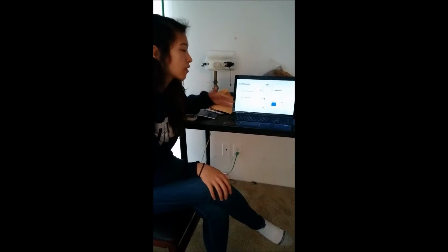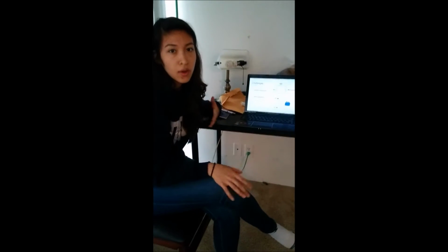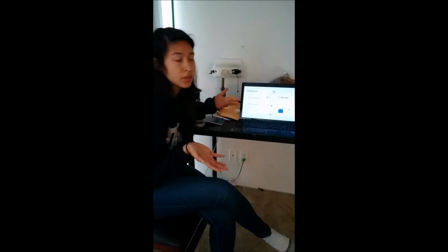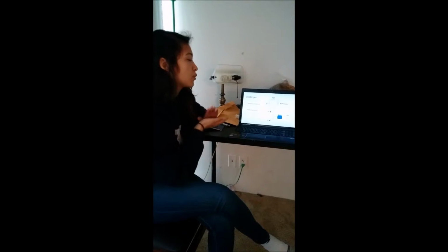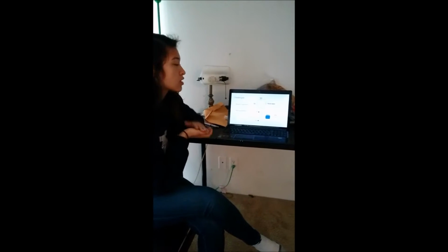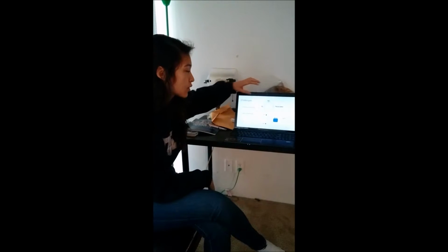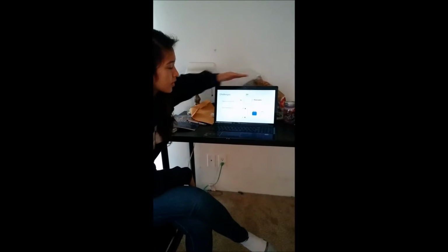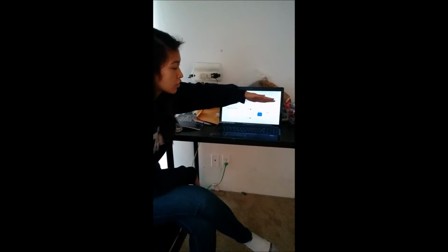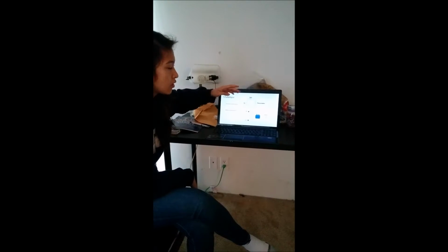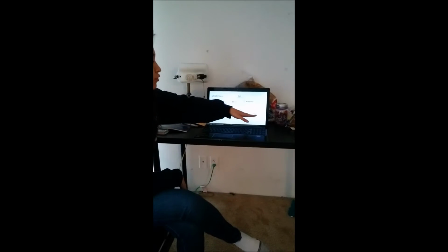Meanwhile, we also had to deal with where to place the motor. How would we create a circuit that would allow current flow in either direction? And we discovered that to do this, we would need to actually connect the motor to two different sources of voltage. And we could then connect the motor to ground such that we could create a variance this way, such that current would flow from high potential to low potential. Alternately, we create a situation where the ground could also act as the high potential point and the current could flow the opposite way to the lower potential.